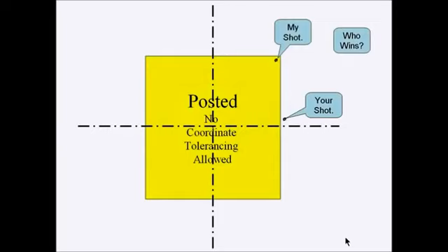When the posted sign appears, explain that if they're using plus-minus tolerances, your shot would be good where theirs would be bad. For instance, if they were using plus or minus 5 thousandths on a drawing, this shot is further away than 5 thousandths. And even though your shot could be as much as 7 thousandths away, it would fall inside the plus-minus 5 thousandths tolerance zone.